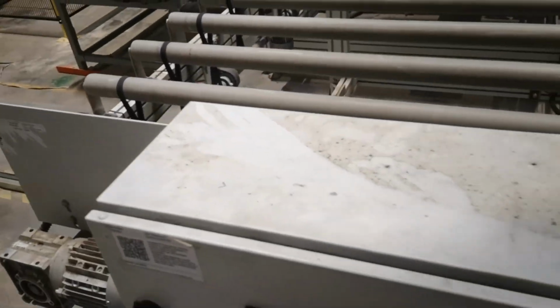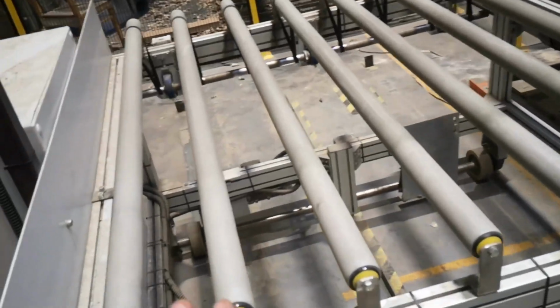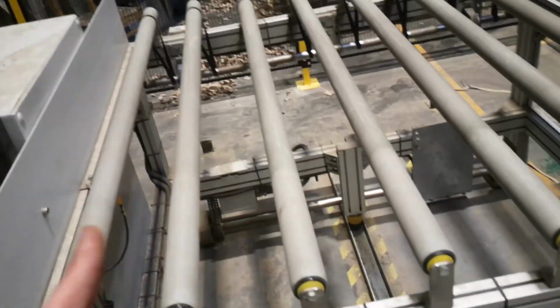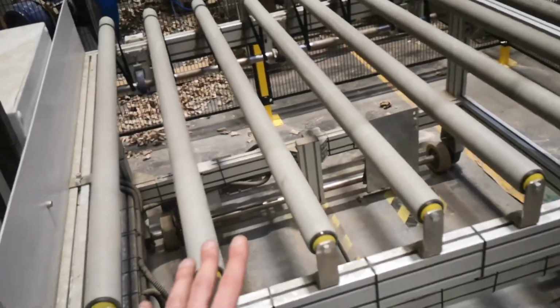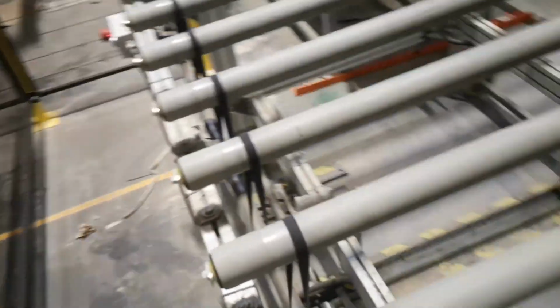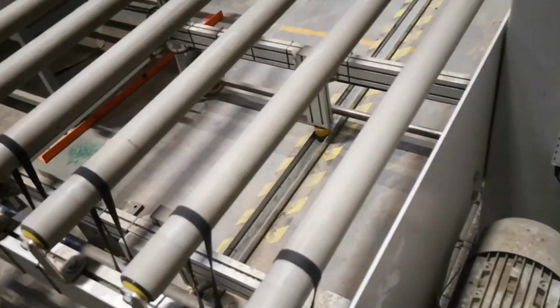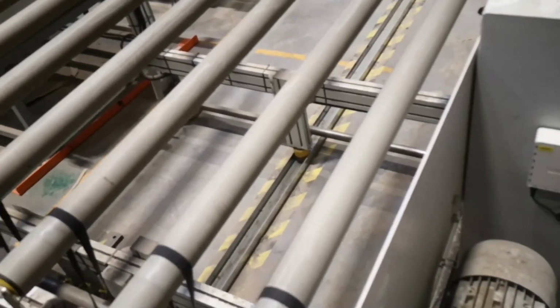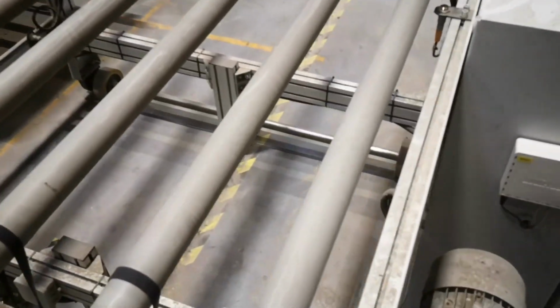So at some points I enable the DC brake. I don't remember the voltage value, maybe 40% or less. I don't want to overheat the motor because, for example, at this position now it's enabled, but I will release it after maybe 10 seconds, I don't remember.